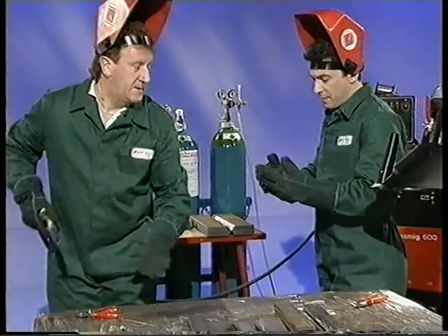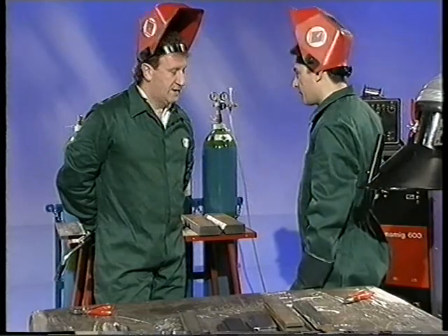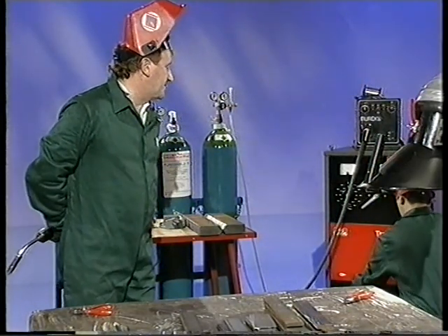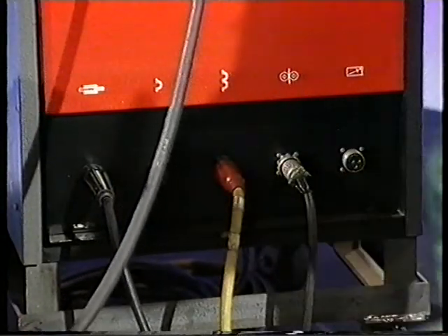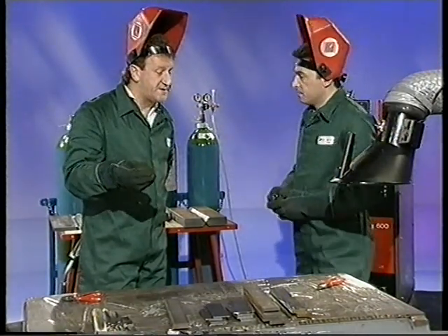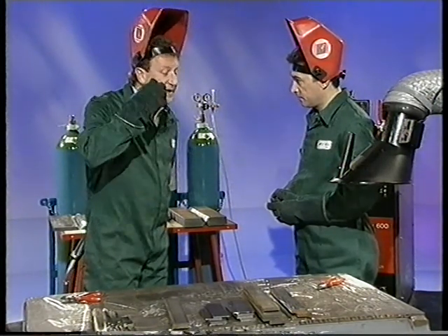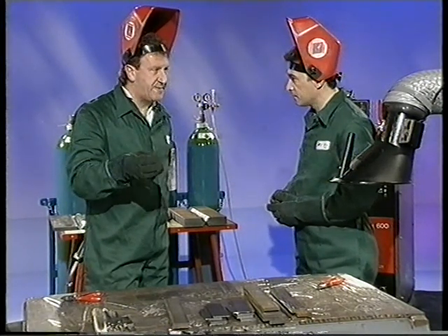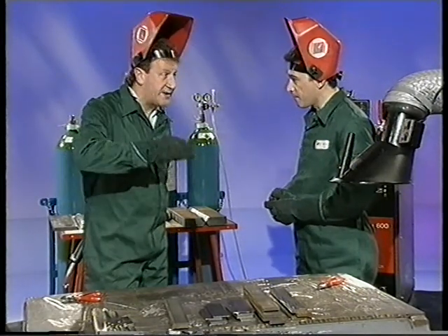Now, we're talking about dip, globular and spray next. Do we need the same inductance? Do I need to put that back? If you'd put the inductance tapping back up, because we're still going to be using a short circuit in this globular dip condition. What happens in globular transfer is that the wire occasionally short circuits the way that it does in dip welding, but it also has more voltage now, so it forms a globule on the end of the wire that drops across into the weld pool as well. It does create quite a lot of spatter, and it isn't a condition that's used very often, but it is a condition in between dip and spray.